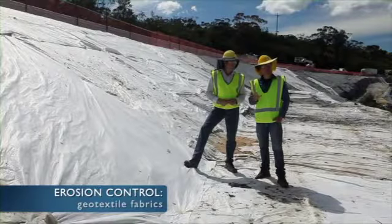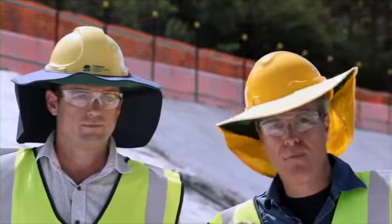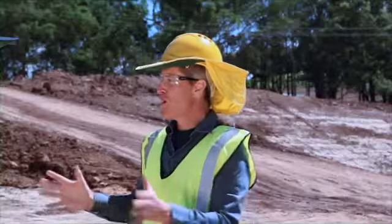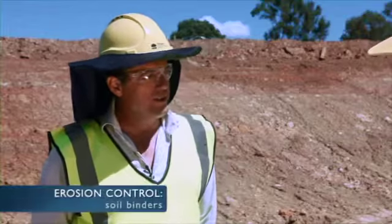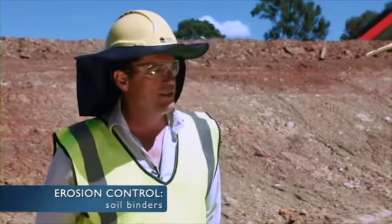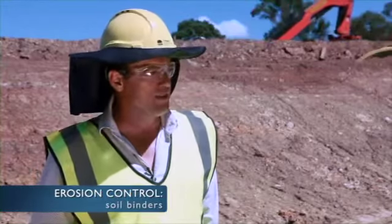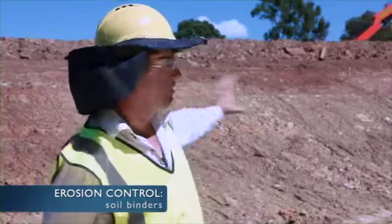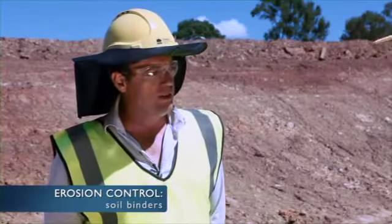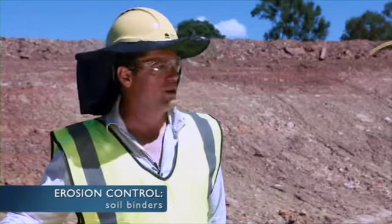Now, there are less obtrusive ways of doing it, and that's using sprays that bind the soil. Let's take a look at that. Chris, soil binders, what are they? Pete, soil binders are effectively a glue. They're used over large areas as a form of temporary stabilisation. Right, now where would you use them? Use them on just about any exposed area on a construction site, Pete. They could be useful on batters like this one behind us here. They're also useful on stockpile sites. May also be useful on exposed areas of the construction site that's not going to be actively worked for a period of time.